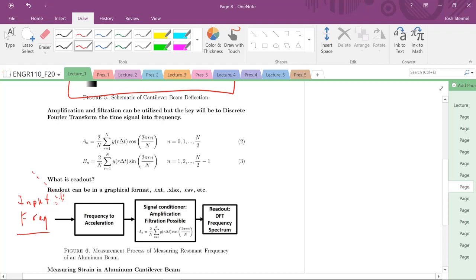There could be one, where if you have a beam that's very well characterized in length, you could calibrate your results. But you actually don't really need the calibration step here as long as your accelerometer is calibrated. So that's an assumption that we make here, that the accelerometer is working fine.